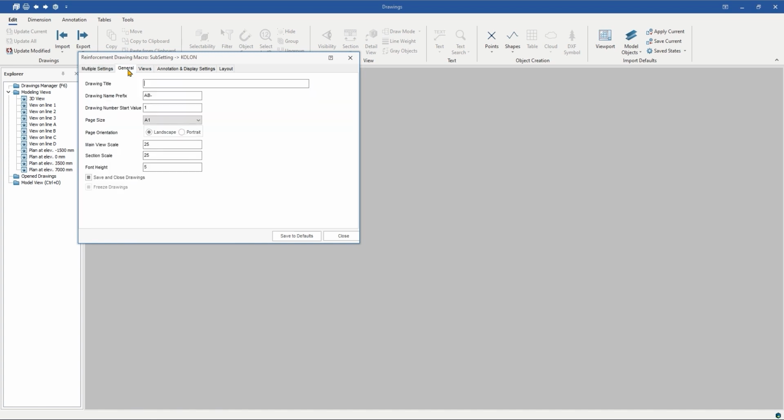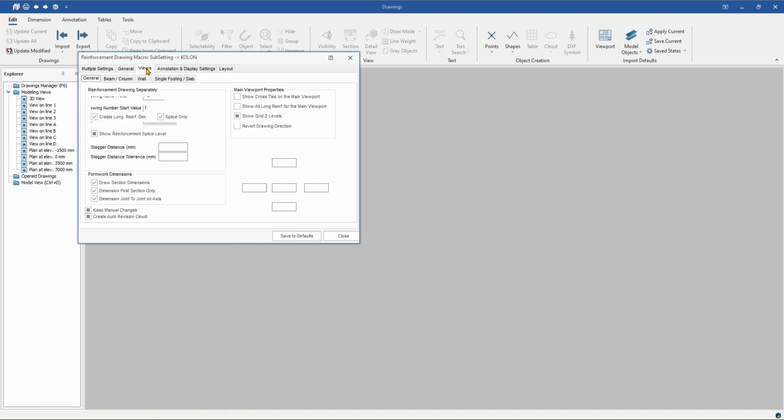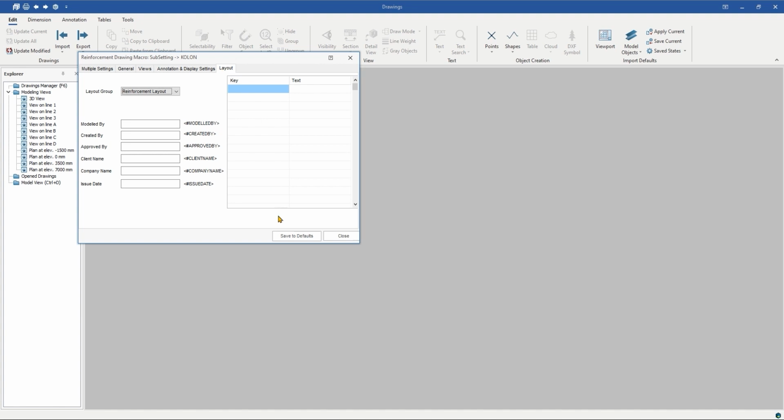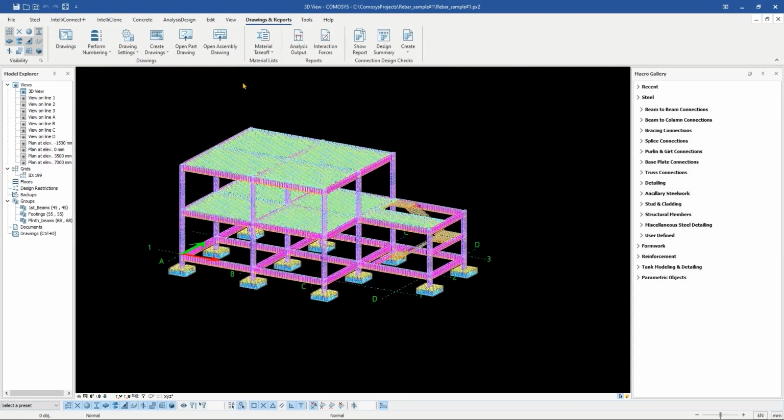User can define drawings properties, control view scales and its display, locations of section views, marking settings, dimension settings, drawing sheet size and several other settings. It is advisable to user to prepare and save these settings in prior, so that the quality of drawings will be good enough for presenting and save lots of time in editing the drawings.